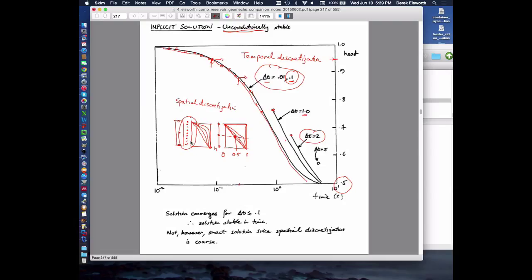An easy way to check it is to take your model, which has a physical attribute to it, has a shape and size and material properties, and you run the model for a given mesh with a given time step. You reduce the time step until you get to the same result at a reduced time step. And then you change the mesh and make it a finer mesh and see if you still get the same result. If you do, then you have a solution. You don't have to worry about it. And you physically solve this issue of being able to make sure that you're in this particular space here. It's good. That's fun. So good.